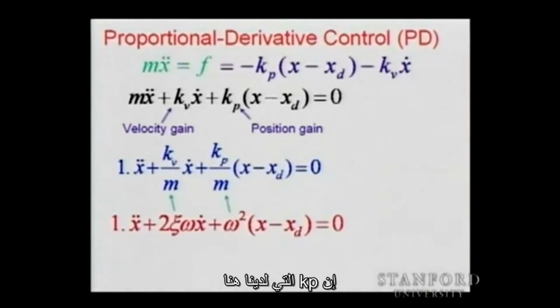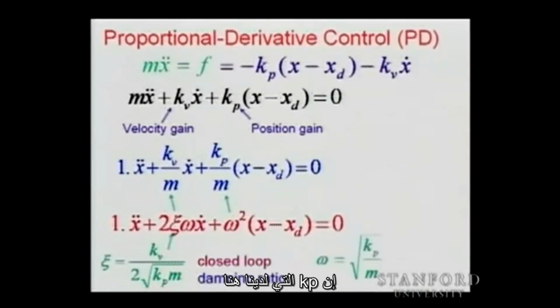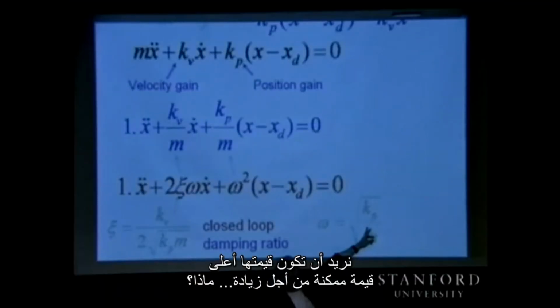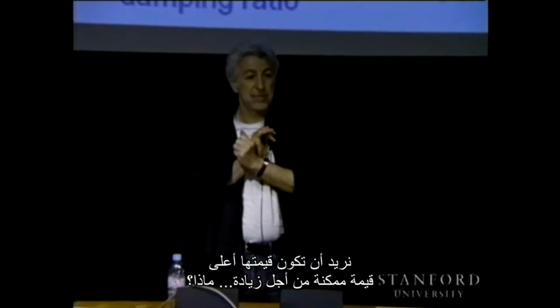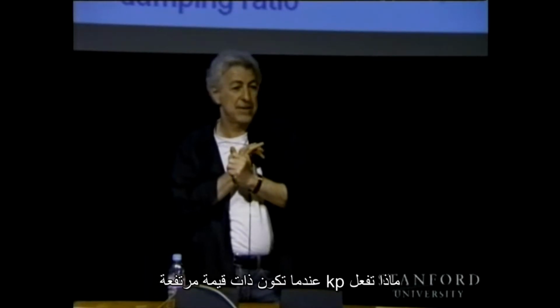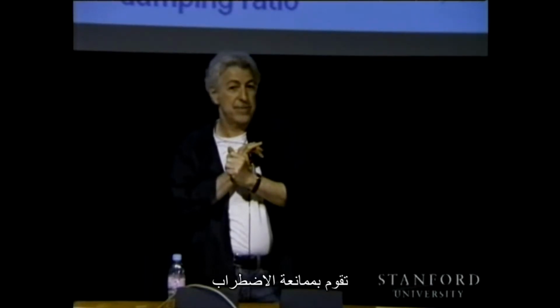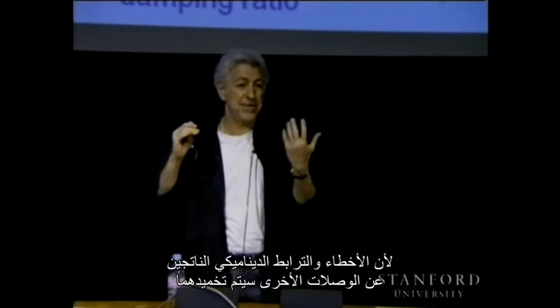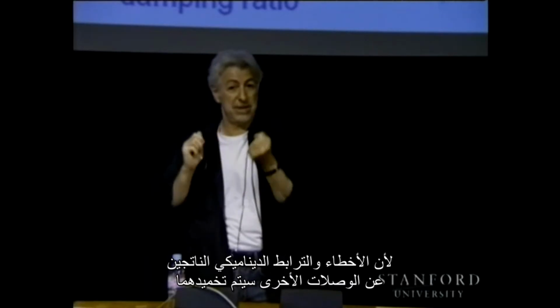So this KP we have here cannot go too high. We want it as high as possible to increase what? What does it do when KP is high? Disturbance rejection, because errors coming, dynamic coupling coming from other links will be rejected. It's stiffer.